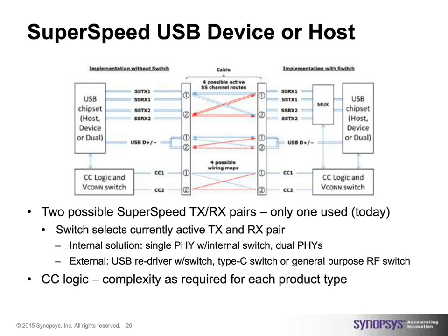So Morten, I see here you've got two separate SuperSpeed data paths to route, but you only need one high-speed data path, and that high-speed data path is shorted together in the connector. Why is that the case? Good question, Chauvet, but it's about reflections. The USB signal is terminated by the receiver at the other end of the cable.